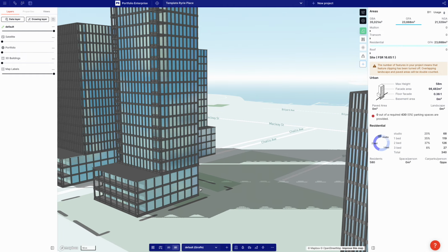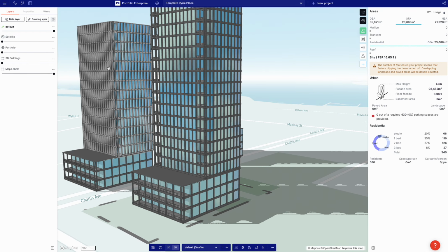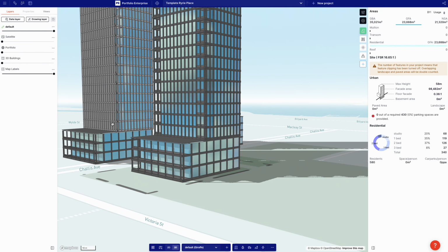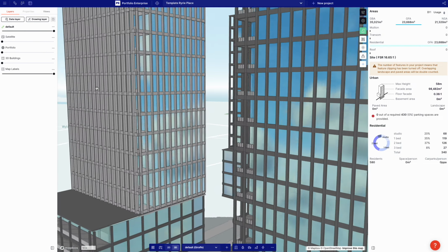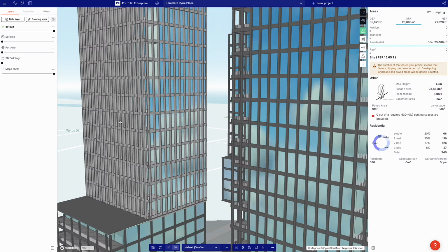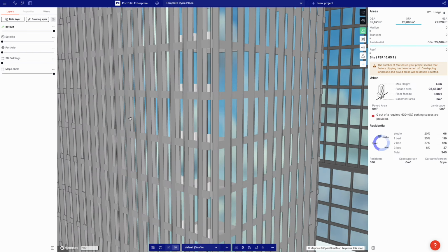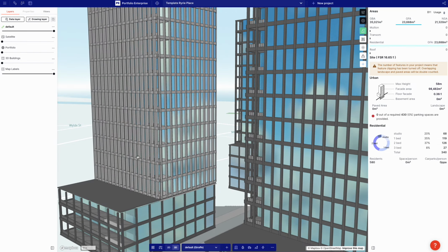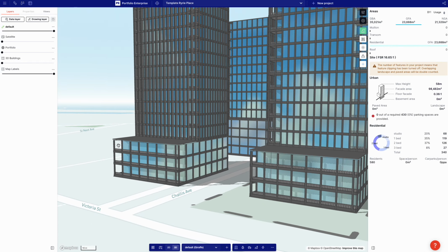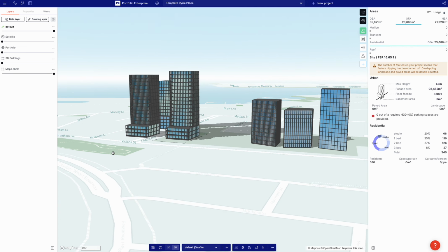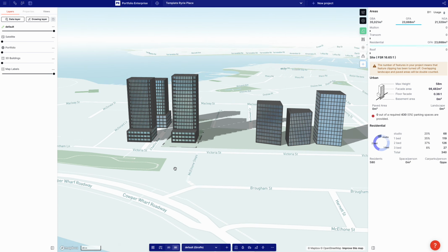So I'm trying to get my camera to the side. For a side facade, like for a west facing facade or a slightly northwest facing facade, this is amazing. Look, there's almost no sun. When the sun is low, you don't see in there. So as a privacy control, just extending those things out is incredible. And that is a very simple lesson of facades that I have learned just from playing with Flow Builder.